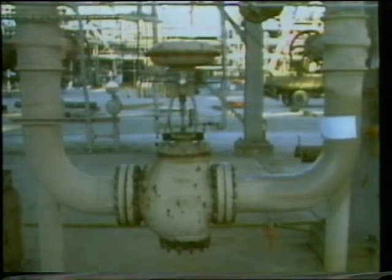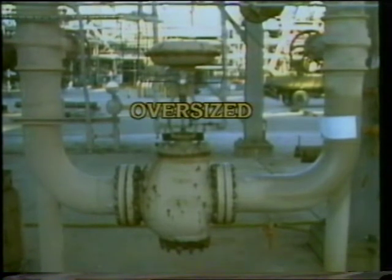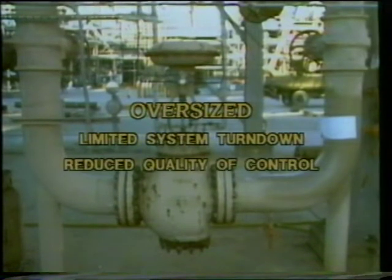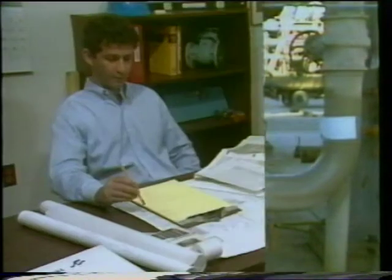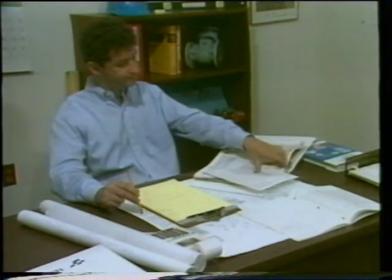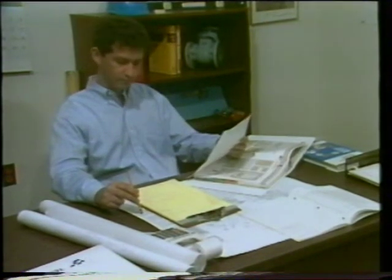Of course, if the valve were significantly oversized, other problems might occur. The valve may be unable to control properly at small flow rates, thus limiting system turndown. System turndown is the ratio between the normal maximum flow and the minimum controllable flow. There would also be a general reduction in the quality of process control. So you can see, even if there is uncertainty in some of the data that's been obtained, it's important not to become too conservative when sizing the valve.